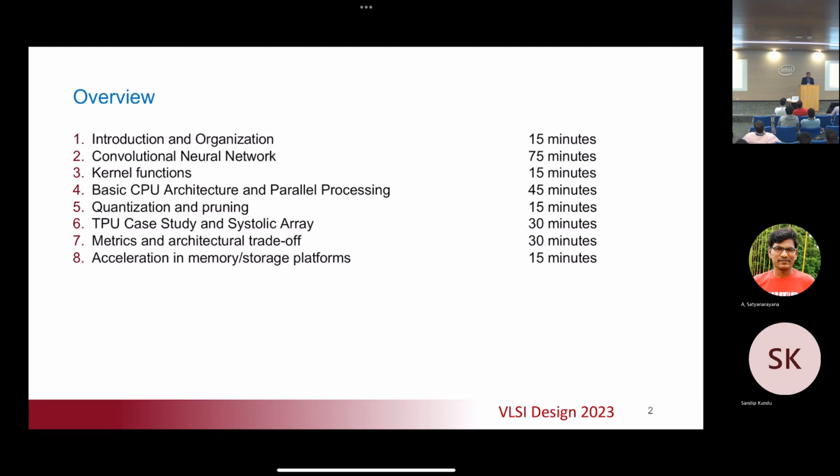We don't try to accelerate every function in the machine learning algorithm. That would be a fool's errand because it's not going to give you that much performance benefit, but it's going to cost you a lot in terms of hardware. So if something takes 90% of your computation and something else takes 10%, and you can speed up the 90%, then a lot of times you have already achieved your performance goals.